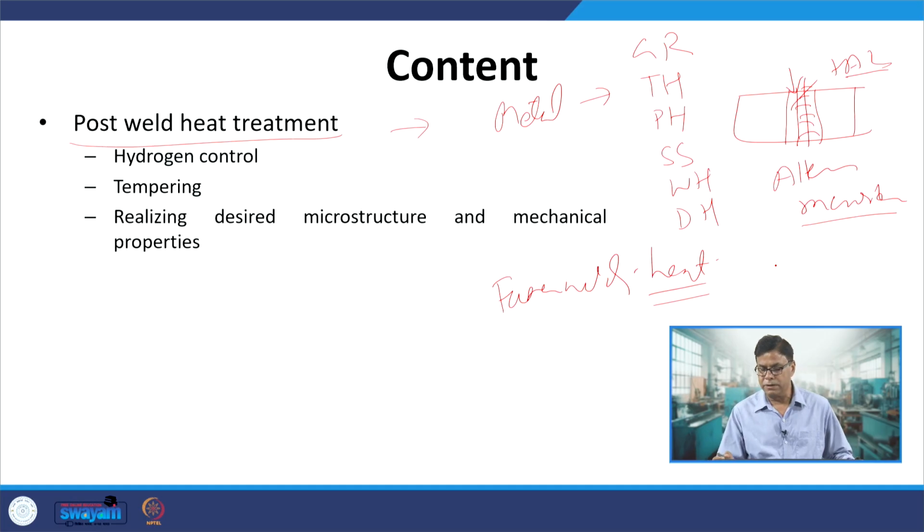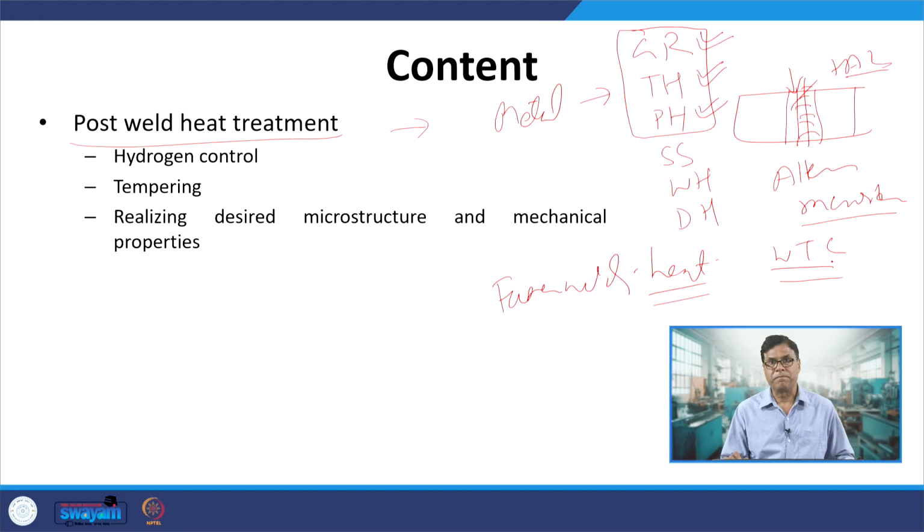and it will significantly govern the mechanical properties and performance of the weld joint, in the case of metals which are strengthened by grain refining, by transformation hardening, or by precipitation hardening. So, the metals which are strengthened by these three methods are affected very badly by the weld thermal cycle which is imposed. Why? Because their microstructure is modified significantly when fusion welding is performed.